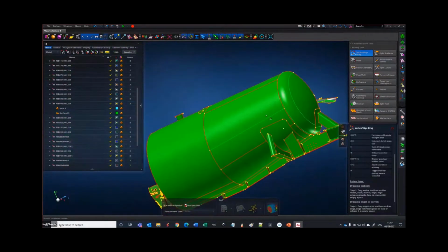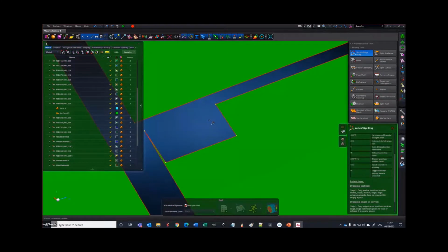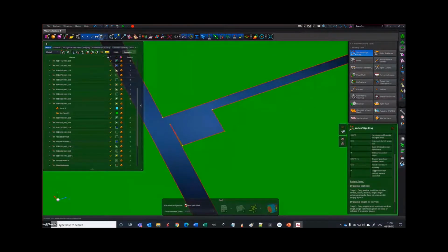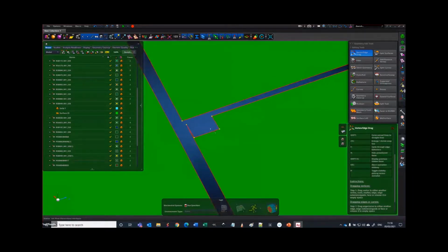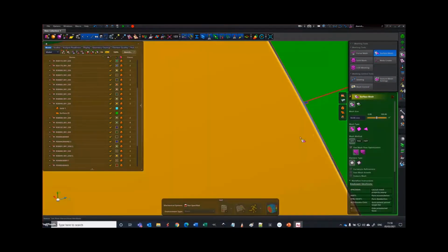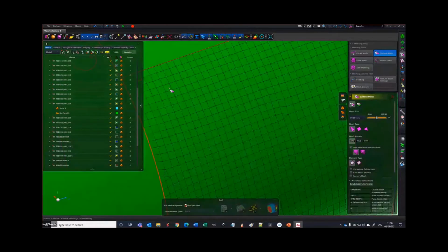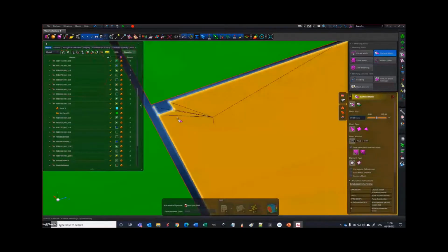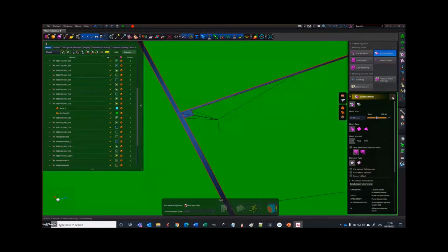Another example, for instance, is one little defect that I am aware of. And this defect that exists in this mid-surface is actually as a function of the original solid that had a defect in there. Now, unfortunately, you typically don't know about these until they start giving you a problem. So, for instance, when you get to the point where you mesh this body, you will get bad elements. Or maybe you'll notice that there is something fishy in there, but it's so small you might literally not even see it. And only when you try to analyze the model will you actually find that there's a problem.